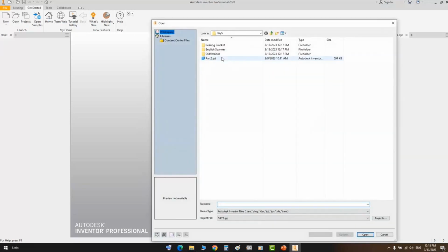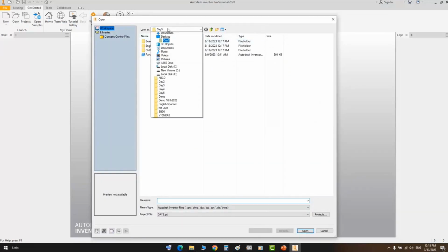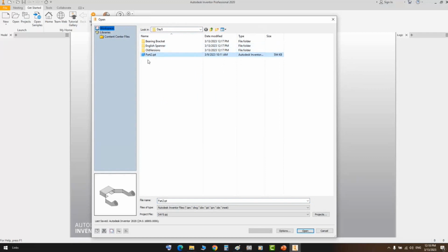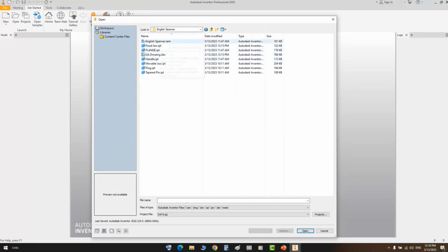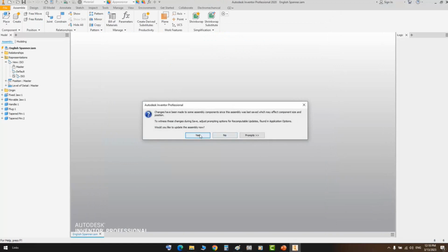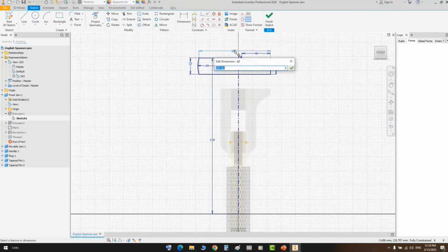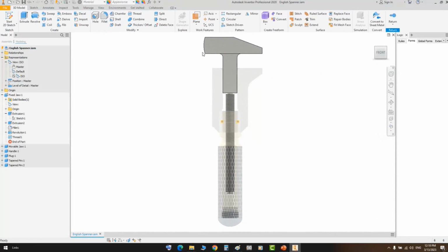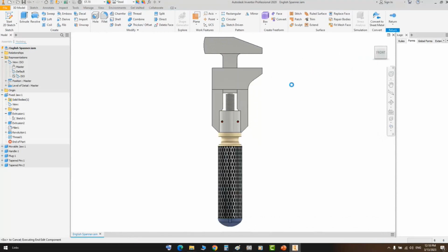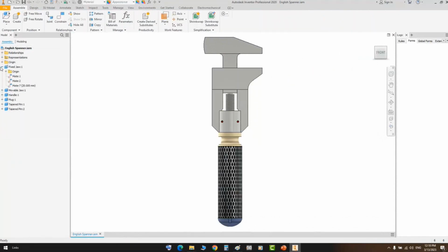Here, for example, now you will get that folder, which is Day5. Inside this folder, you will find those parts. You can open, for example, the assembly of that one, and re-modify this part again by selecting the sketch and changing the length back to 80 millimeters, and now you get the modification. So you can take a copy from your project. That's in case of using Autodesk Inventor.